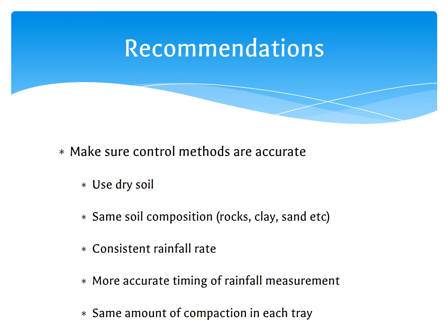A more reliable rainfall simulator would need to be used to ensure the rainfall rate was homogeneous over the lab session, and the timing of rainfall collection should be precise. In this experiment, the rainfall collection times were not even for both labs. Some were taken 15 minutes apart, others 9 minutes apart. Therefore, more rainfall samples were taken when there was less rain, at more frequent intervals, and the results would be more accurate for these.